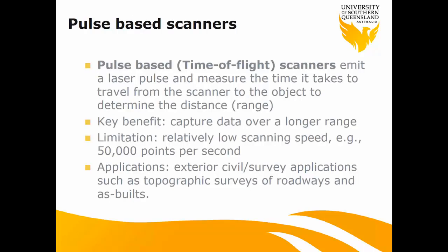Let's first have a look at the pulse-based or time of flight laser scanner. This one directly measures time, and the advantage is longer range, up to 1 kilometer or even several kilometers from the instrument to the object you are interested in.